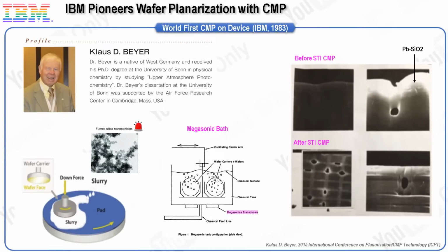I also recall how my fab manager initially reacted to the CMP process, relegating it to a specialized area and denouncing the abrasive as a source of contamination. Despite these challenges, deploying CMP tools within clean fabrication facilities marked a pivotal shift. The first successful adoption of CMP relied on developing effective cleaning methods for the polishing slurry. Megasonic cleaning, using Triton X as a surfactant, proved to be a breakthrough. This method enabled the removal of polishing slurry from single wafers without causing scratches, addressing significant concerns about the CMP process.